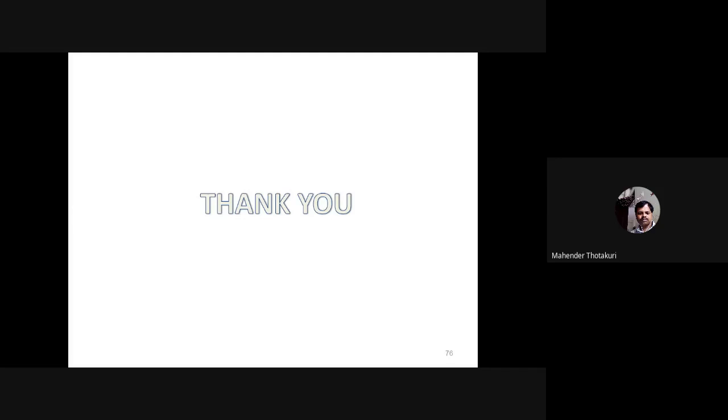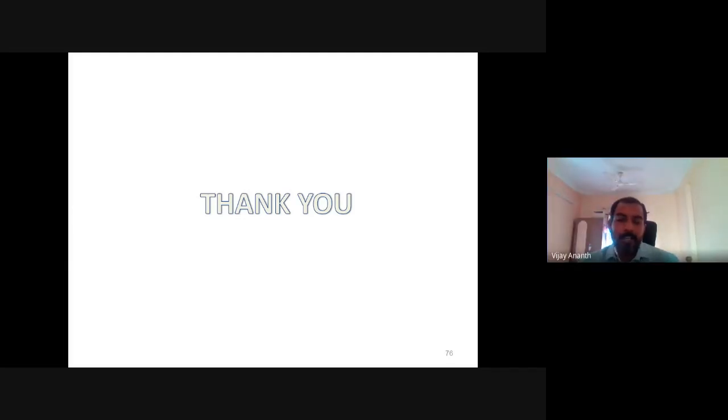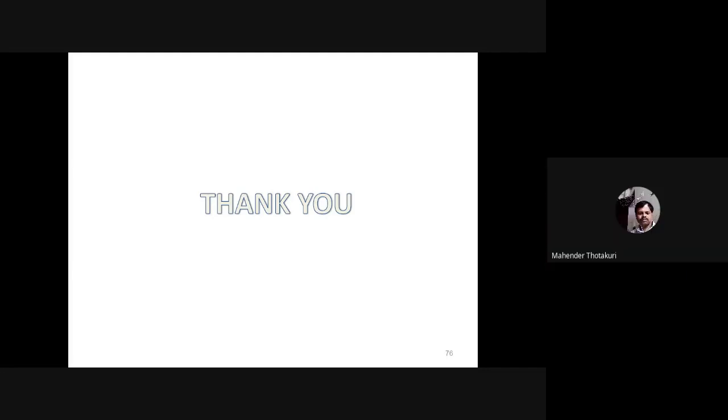Yes, sir. For the second phase particle, in my case, aluminum 6063 is alloyed with magnesium and silicon. While we are heating the component, this magnesium and silicon will form Mg2Si, magnesium silicide. The melting point of this Mg2Si is somewhat lower compared to our aluminum alloy.